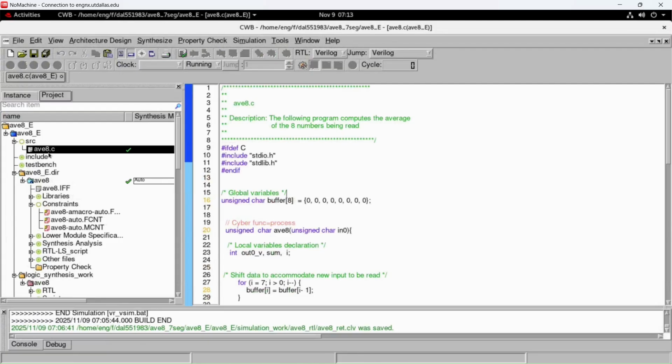The options that we get from high-level synthesis is we can use the PDL language or the C or the SystemC. So you have a wide variety of languages with which you can compile your code and then get the RTL. As you know, high-level synthesis basically converts your C code to your Verilog code, C or any other code of your choice, and it does a few processes which I'll be going through in detail, and then it produces the Verilog code with which you can do further simulations.